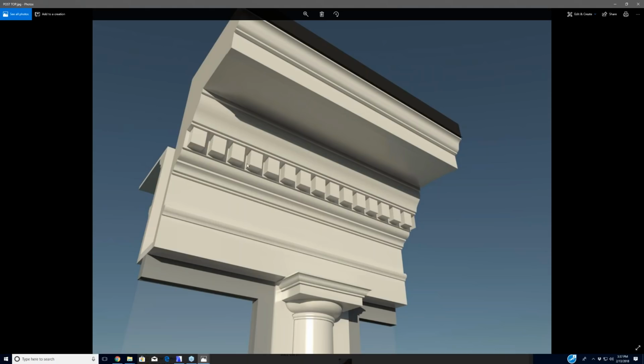Now, I can't get them to skip like that in a complex profile. So I will, in plan, draw this complex profile just like a wall, and then in plan put one tiny little slab, and then I'm on a PC, I'll use a Control U or a Command drag to copy these at the correct spacing. So I'll measure the dentil in the field, and then I know it's a 3/4 of an inch gap, and I'll march them all the way across and then group them. You could, if you wanted to, turn them into a library part. You could turn them into a morph, just so you don't have a whole sea of these little slabs all over the place. So it's really whatever you think is easier.